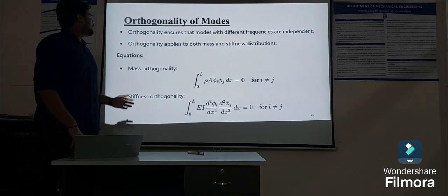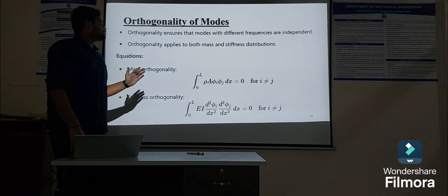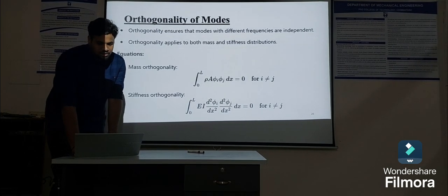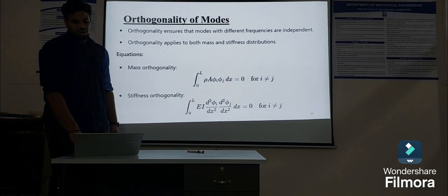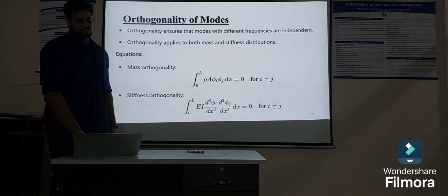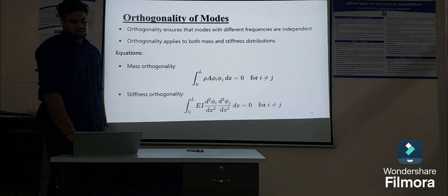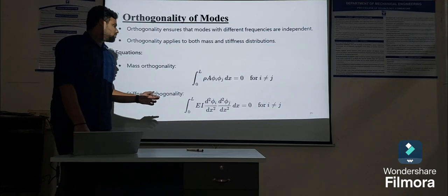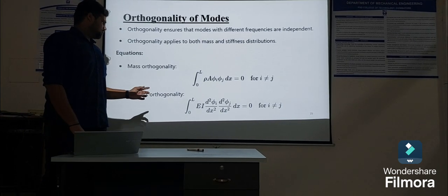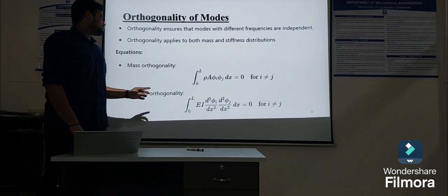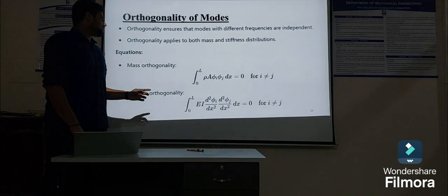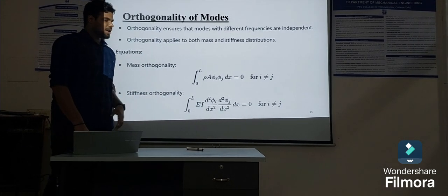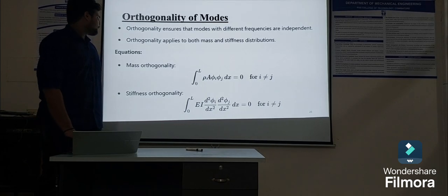Orthogonality of modes. Orthogonality ensures that modes with different frequencies are independent. Orthogonality applies to both mass and stiffness distributions. The mass orthogonality equation is integration of 0 to L ρ into A into ψ_i into ψ_j into dx is equal to 0 for i not equal to j.